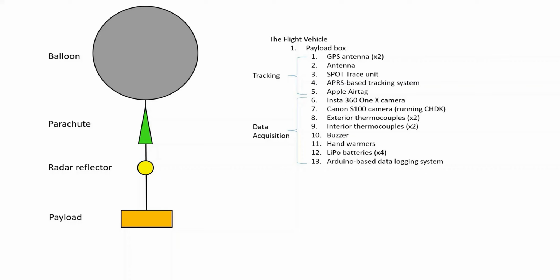So in addition to the payload box, the other thing that is a major component of the flight vehicle is the lift system, right? This includes things like the balloon and the helium. We're going to see later that you actually have to have specific types of lines connecting all of them. So the lines that you connect anything together with have to be able to break under 50 pounds or less of tensile load.